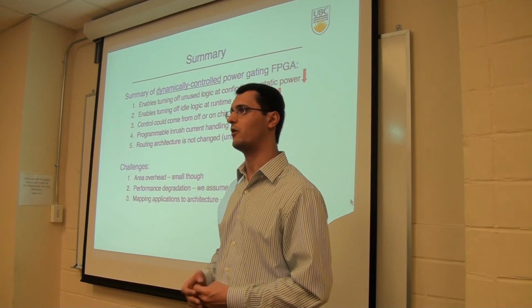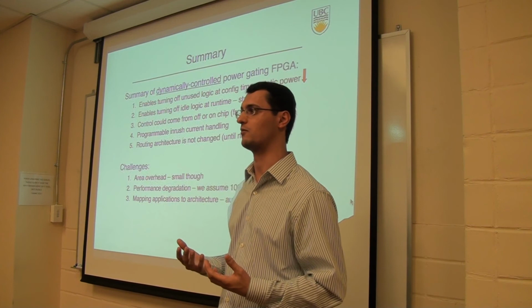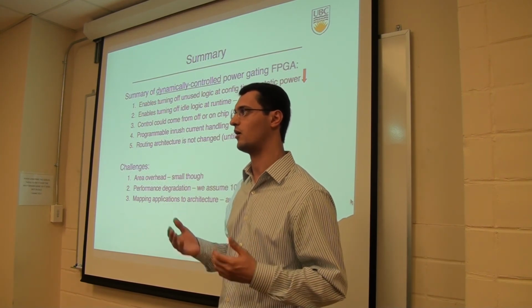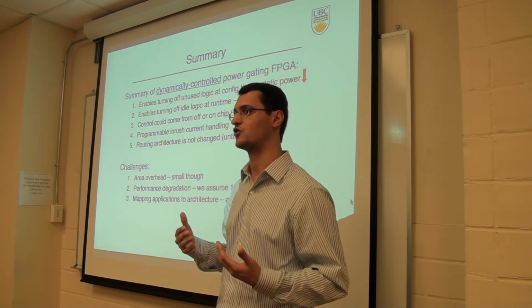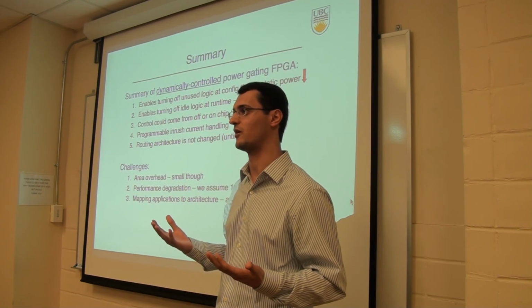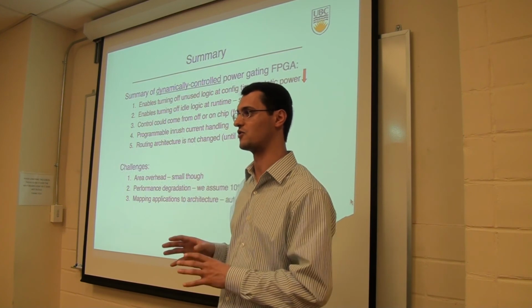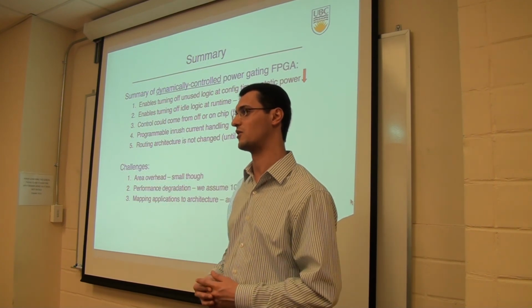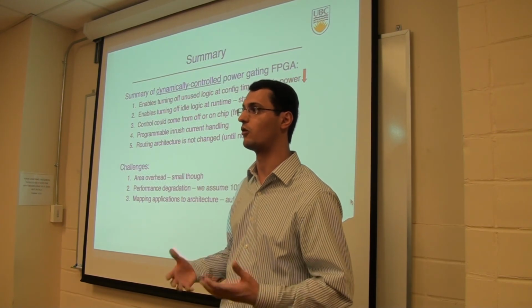Yeah, I think what you are saying completely makes sense, because the designers should have this in mind when they design their applications, similar to what ASIC designers have, right? And this should fit into the design flow in some format to tell the tools that this is power domain 1, this is power domain 2, this is the power controller, and these are the control signals that control the power domains. So yeah, it makes sense, but my focus in this work was on the architecture itself that supports all of this.